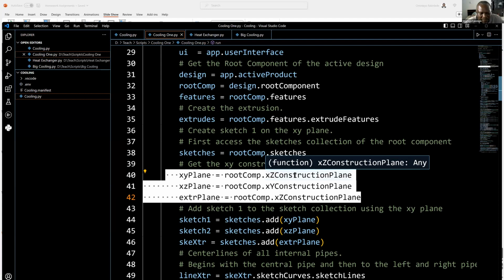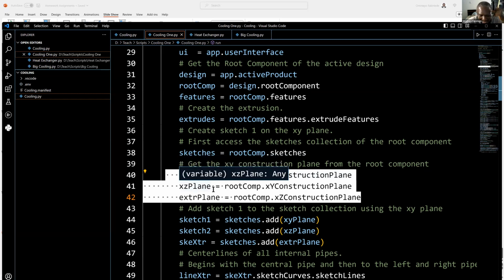It is so because if you look at your axes, the people who created Fusion 360 think of the Y-axis as pointing up, the X-axis pointing to your right, and the axis toward you being the Z-axis. But the way I think, the one that points up and down is the Z-axis. So these 3 statements give me the correct XY plane the way I think, and the correct XZ plane the way I think, and because I already know how they think, I'm able to just continue working the way I want to work.